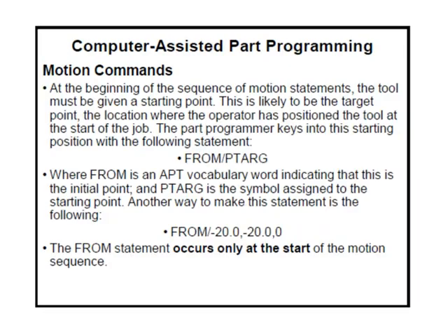Similarly, the target point can be defined and the motion command written, and this pattern can also be used. From the target point you can go to x-axis minus 20, y-axis minus 20, and z-axis 0. This is the way it can also be written.